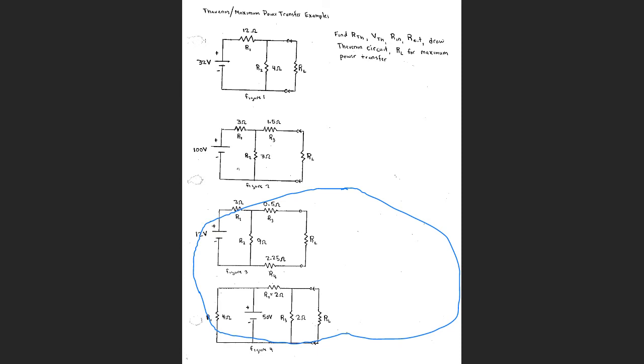All right, now I'm going to put this resistor back in there. And now I'm going to find my Thevenin resistance. And that's what I'm going to replace that with the short circuit. And as I was saying, when I do that, and I put the wire here, it puts these two in parallel. So if I'm looking in here, here's my eyeball, I'm looking in here.